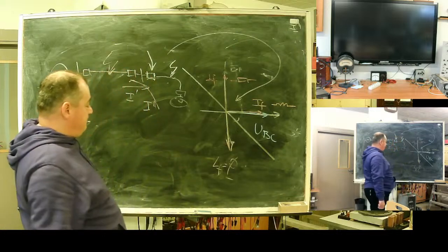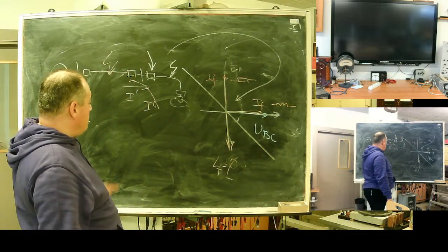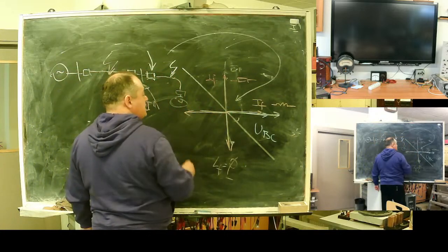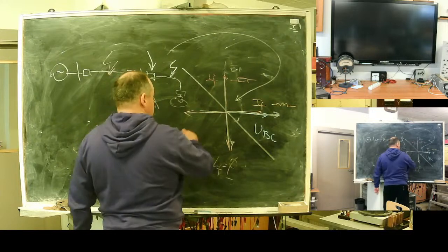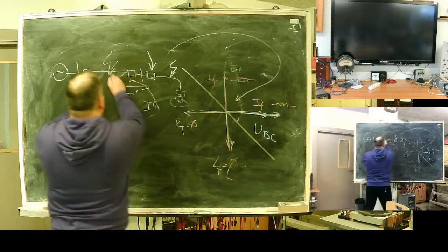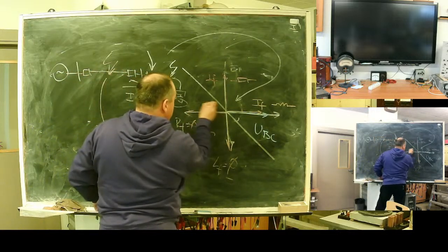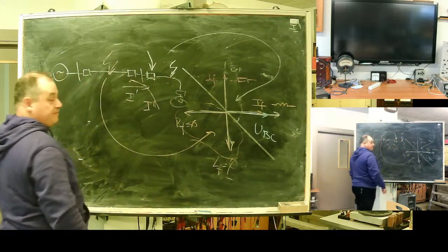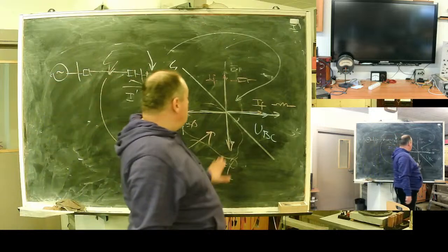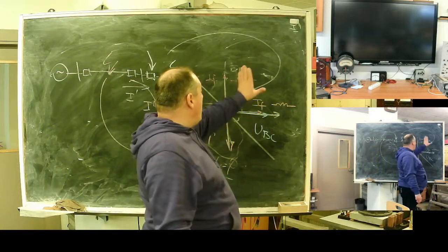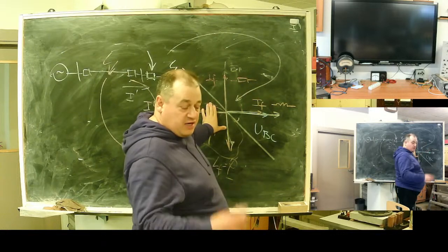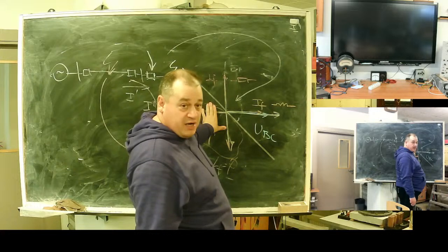In case R fault is 0, again I will see 90 degrees lag but with a minus sign. So all these faults will be in this area. All possible reverse faults. So, white area, operation allowed. Red area, this brick color area, operation should be prohibited. Yeah?